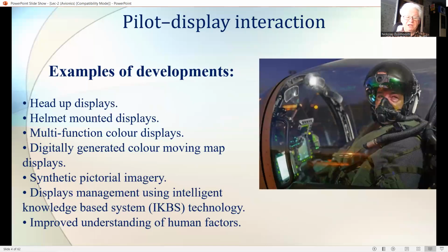Examples of these developments are head-up displays, helmet-mounted displays, multifunction color displays, digitally generated color moving map displays, synthetic pictorial imagery, display management using intelligent knowledge-based system technology, improved understanding of human factors, and involvement of human factors specialists from the initial cockpit design stage.